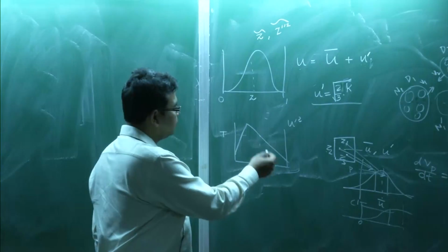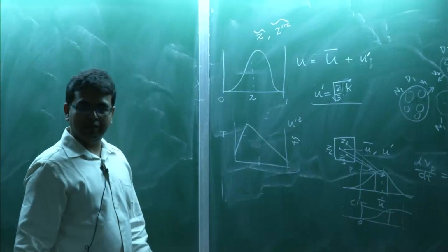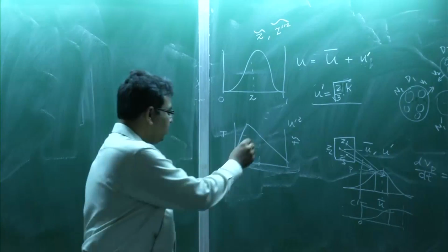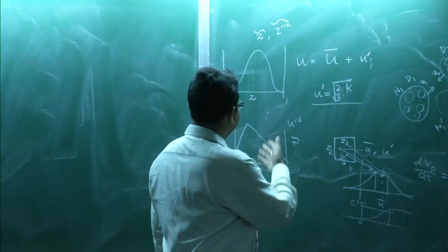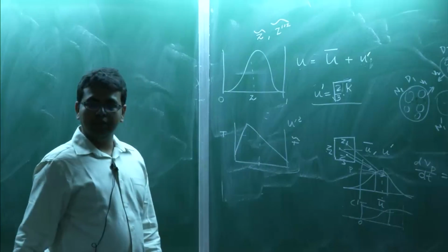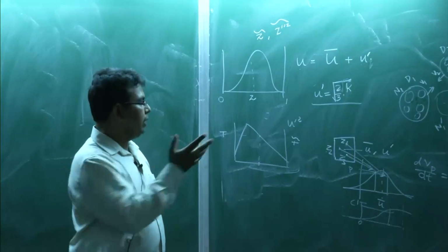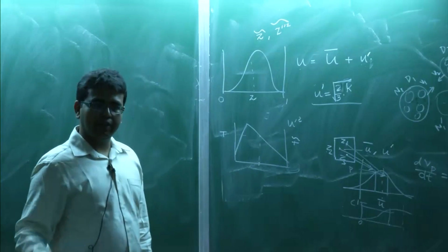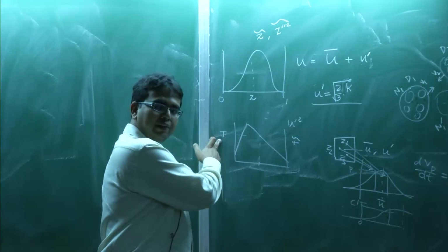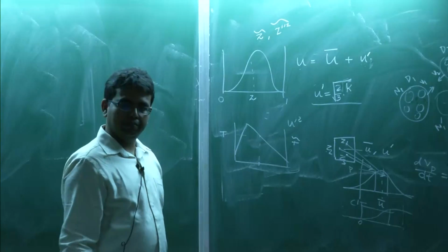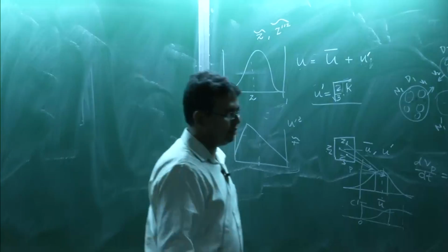So far people have used the mean temperature. Mean temperature and instantaneous temperature are different, right. So, we should use this instantaneous temperature in our model, okay. That is what can be done using the mixture fraction concept. If you solve for the mean and variance of mixture fraction, you can sample the PDF and get the instantaneous mixture fraction, and from that you can get the instantaneous temperature and instantaneous composition also, right. The composition also you know as a function of Z, so you can get that.